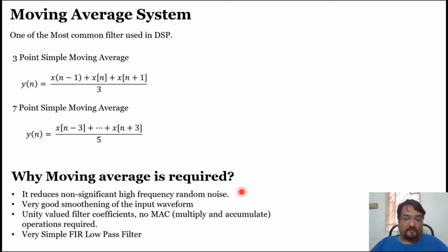Okay, it also depends on where you are taking the EEG. There are different levels of taking EEG based on invasivity, whether you are opening the skull or not, and even after opening the skull, at which level you are taking it, and accordingly your range of frequency will differ. The point of interest, or why I am saying this, is that high frequency noise removal is one of the very essential and basic steps in any biomedical signal pre-processing algorithm. So one of the main points is that it will remove the high frequency noise.